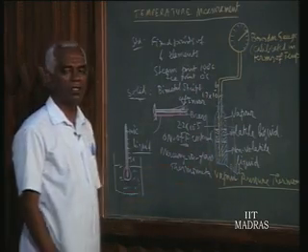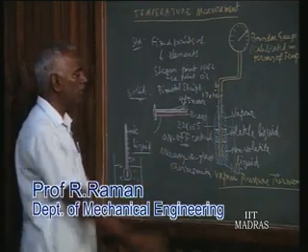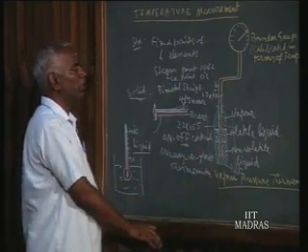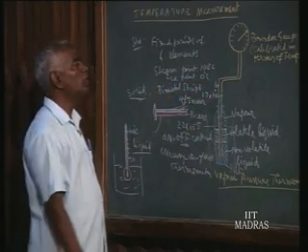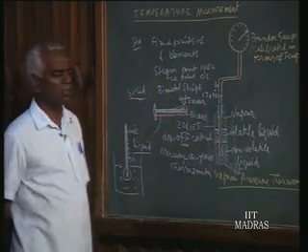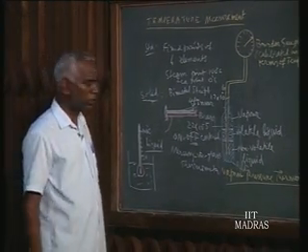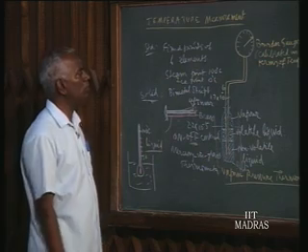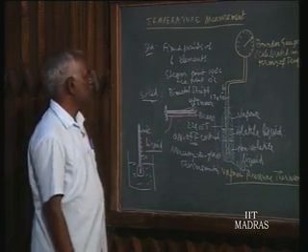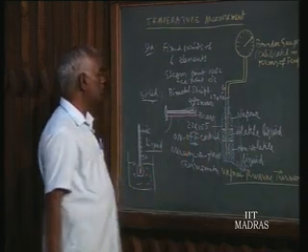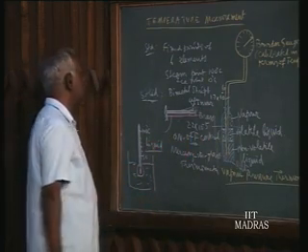These are often used in automobiles and cars, where the radiator water temperature is measured by a bulb like this vapor pressure thermometer, and the meter is put in as one of the dashboard instruments for the driver to see whether the temperature of the radiator water has increased. If it has increased, that means the water quantity is reduced, and then he is supposed to pour some more water into the circulating system. So for temperature measurement, the physical expansion of matter is made use of.